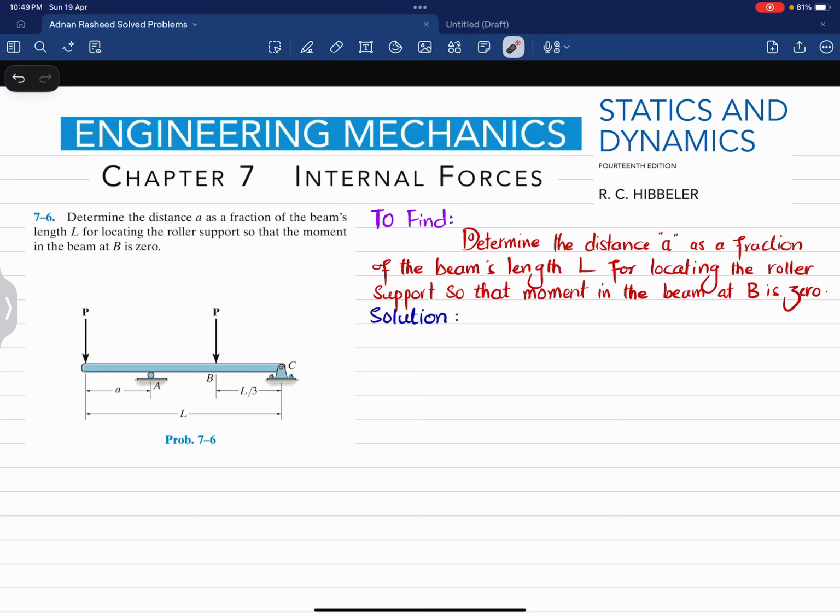Welcome back. In this video, we are going to solve problem 7-6 that is taken from chapter number 7, Internal Forces, and the book name is Engineering Mechanics, Statics and Dynamics by R.C. Hibbeler, 14th edition. The statement is: determine the distance A as a fraction of the beam's length L for locating the roller support so that the moment in the beam at B is equal to 0.